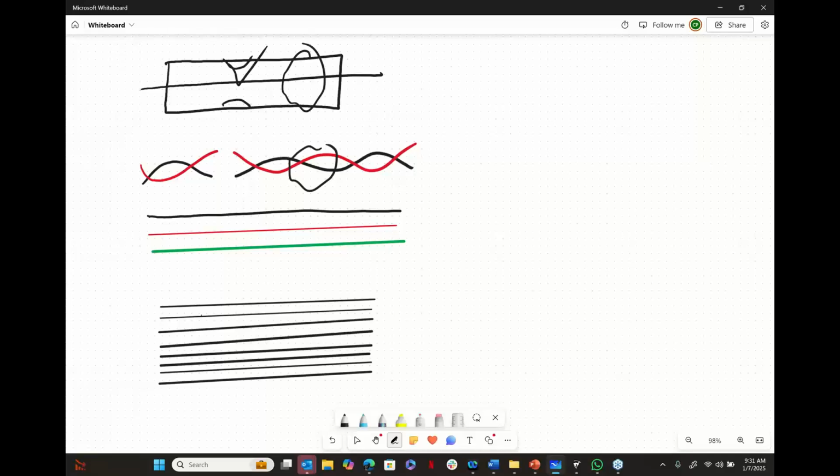We have an issue in twisted pair cable, what we call splits and resplits. Picture if you have a 100 pair twisted pair cable that got damaged or cut at some point. Well, when somebody has to go in there and splice all those pairs back together, they're going to make a mistake probably and get one of those pairs crossed. We call those splits and resplits. And when you go back to add digital services later on, somebody has to go and find where those splits and resplits occurred. TDR is your best man or woman for that job.